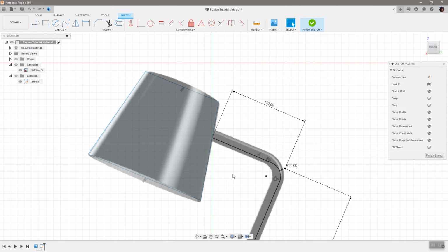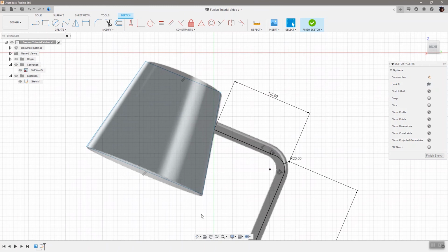And the next thing that comes to mind for me is that the orientation of this lamp is important. And I can think of a couple of ways to do this. This lamp and that end, they look to be parallel, or this could be perpendicular. So let's do perpendicular because we haven't done that one yet. So hit the escape key, say perpendicular, and make this bottom line perpendicular to that line. Now, keep in mind that because these two are parallel, that'll mean that this line is also perpendicular to that line. It's the geometry you learned back in grade school a long time ago. You'll get better at it, I promise.